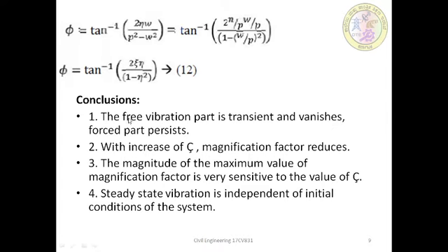So finally, what is concluded is that the free vibration part is transient and vanishes, while the forced part persists. With an increase of the damping ratio, the magnification factor decreases, and the magnitude of the maximum value of the magnification factor is very sensitive to the value of the damping ratio. The steady state vibration is independent of the initial conditions of the system.